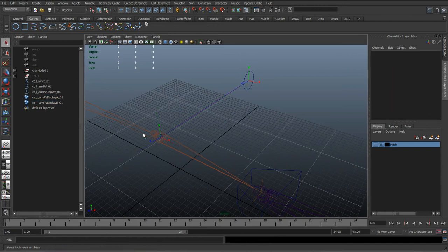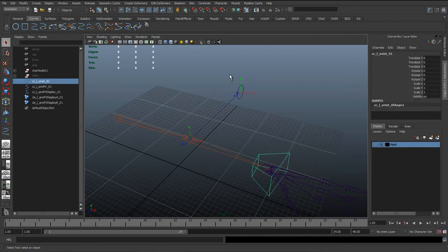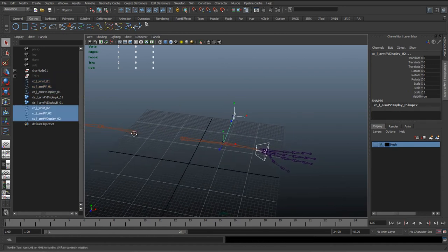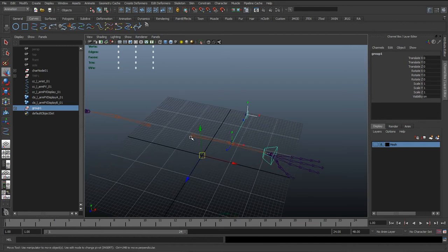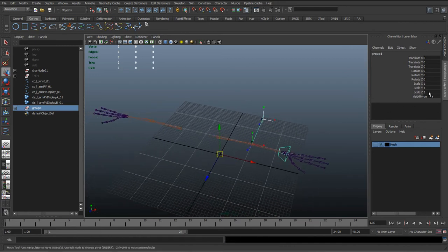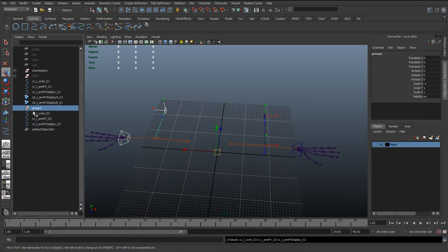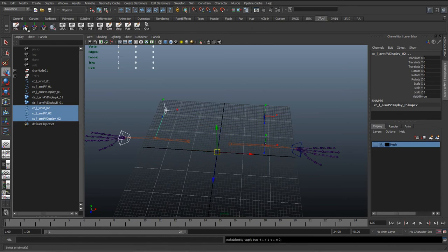So what we can do here now is I'm going to start mirroring this across. So selecting these three curves, I'm just going to hit Control D to duplicate them, Control G to group them. Because group creates its pivot in the origin, this basically means I know that the character's based on the origin, so I can just add a -1 to the scale, and this is just going to flip it over. So this avoids us needing to move each individual thing over and rescaling it or removing all these CVs. And all I can do now is just select them in the outliner, hit Shift P to unparent, delete the group we made because we just made it to mirror it across, and we'll just delete history, freeze transformations.